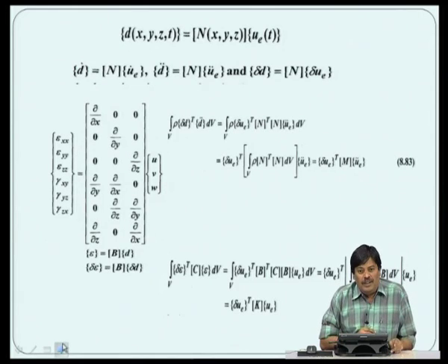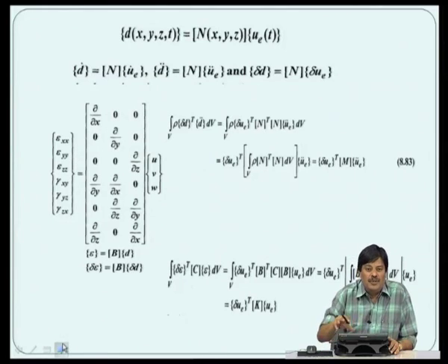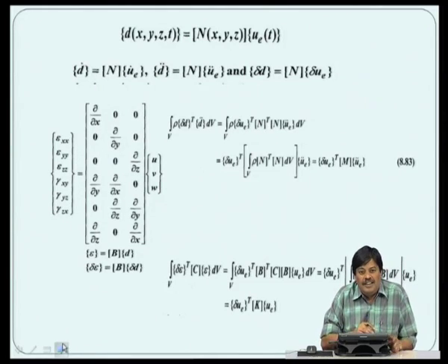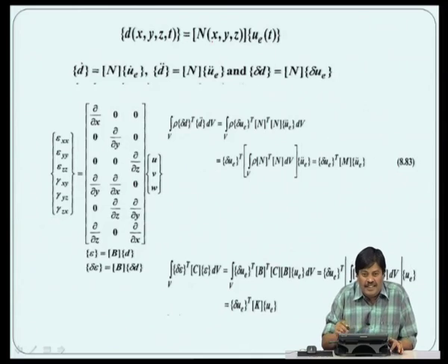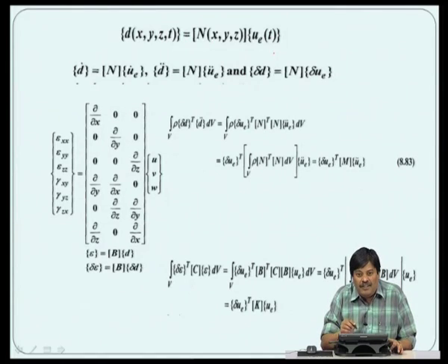Before we do that, we said that in finite element we assume the variation over each element. That is, the variation can be expressed in terms of the shape functions, which I talked about in the first slide, multiplied by the a n of t. The a n of t is the elemental displacement vector of the element, which I call u e of t.